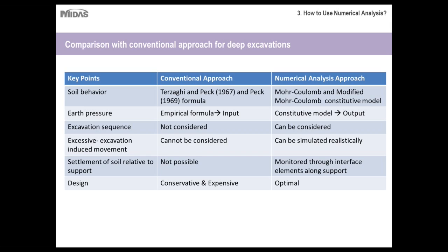Then excessive excavation induced movements cannot be considered under your conventional approach, which can be easily simulated realistically under numerical analysis approach. And settlement of soil related to the support, it's not possible to account for this kind of relative settlement using conventional approach, because the formulas are not tuned to accommodate these kinds of variations.